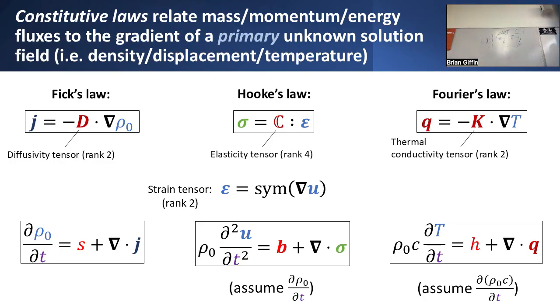Hooke's law is actually somewhat similar, although the interpretation of it is a little bit different. But the idea is we can similarly define some relationship between the stress in some block of material and the corresponding strain in that material, as you're probably used to thinking of it. In a one-dimensional sense, this makes things a little bit easier to swallow. You're probably used to thinking of stress equals Young's modulus times strain. That's certainly an example of a constitutive model that characterizes linear elastic behavior, but in a one-dimensional sense.